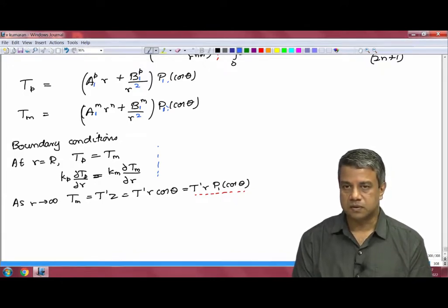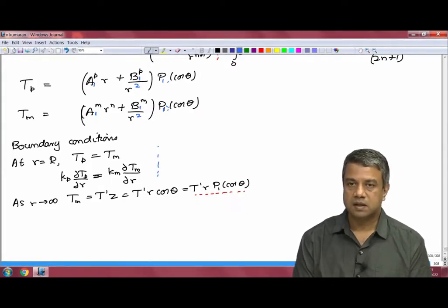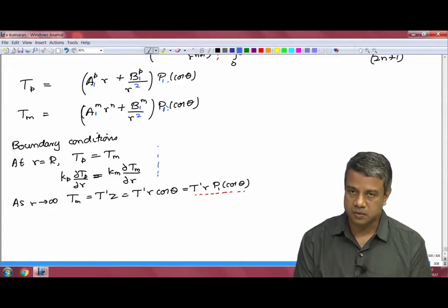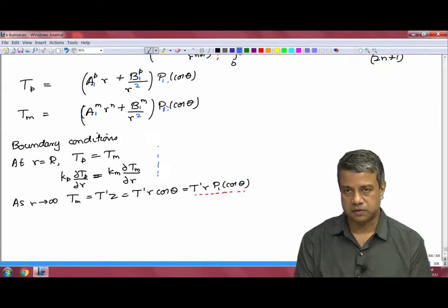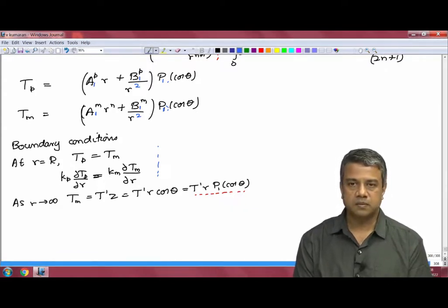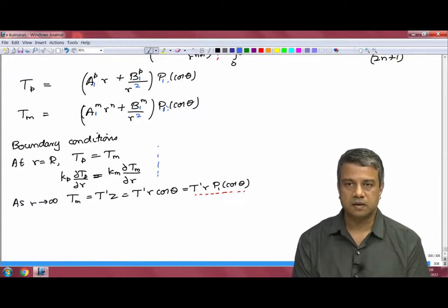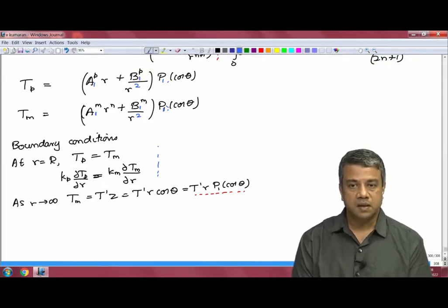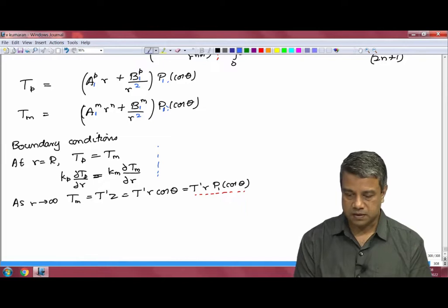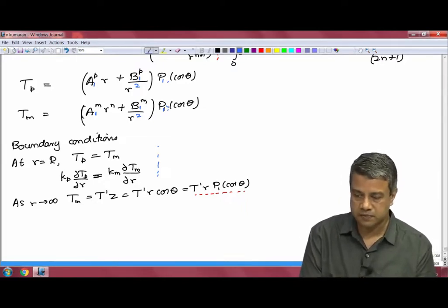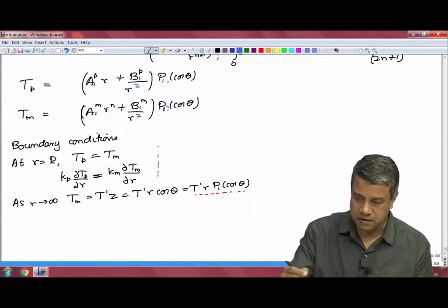So, for P2 for example, if I expand out the equation and the boundary conditions, the boundary condition at infinity is 0. The boundary condition at the surface, the coefficients are related to each other. There is no inhomogeneity in these boundary conditions, and the equation is satisfied if the coefficients are 0. The only case where the boundary condition is not satisfied is for the coefficient of P1, because I know that for the coefficient of P1 the temperature field is non-zero at infinity. Therefore, I can set all coefficients equal to 0 except for the coefficients for n is equal to 1 for the Legendre polynomials.